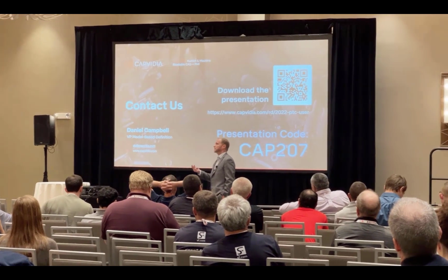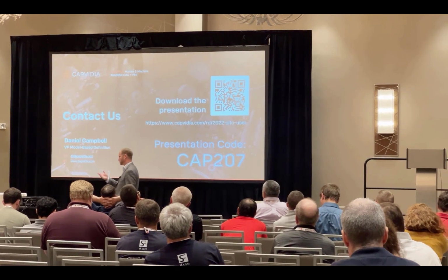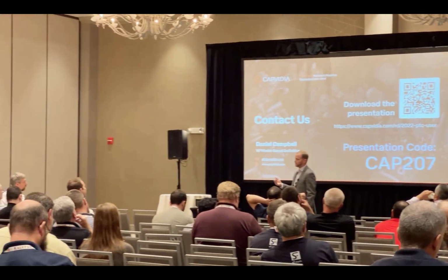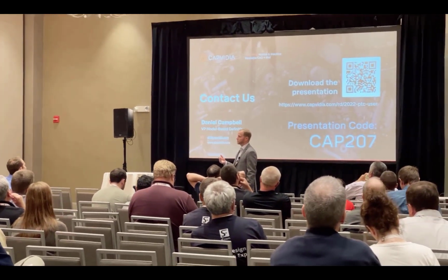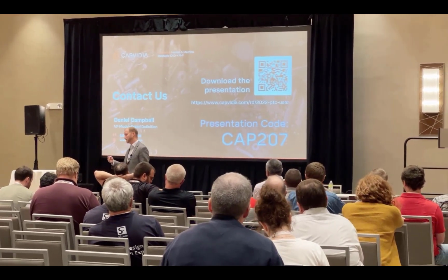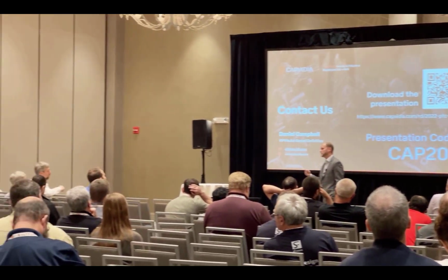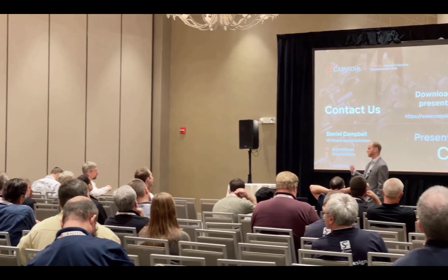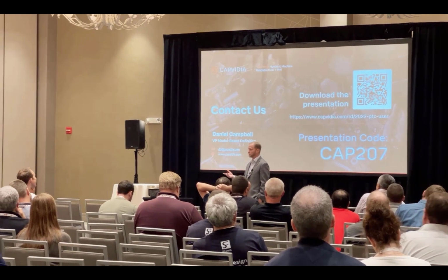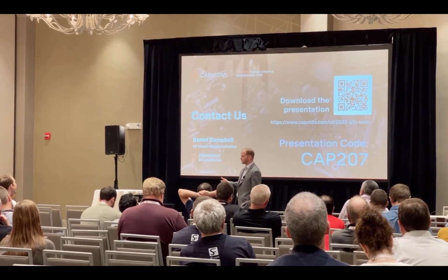There are a couple of different ways that you could interface with CAM software or with machining in general. One would be generation of the CAM program itself. For that, I'm not aware of any CAM tool that's doing anything with QIF. But to be honest, I'm not aware of many CAM tools that are doing a lot with PMI. There are use cases for the use of some callouts on a part in terms of generating a CNC program. But a lot of the annotations on the part would simply be ignored. Maybe you could look at surface profiles and things like that.